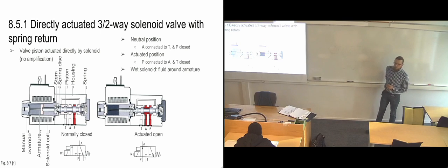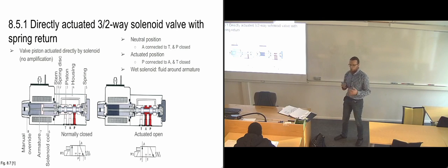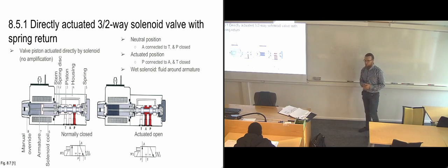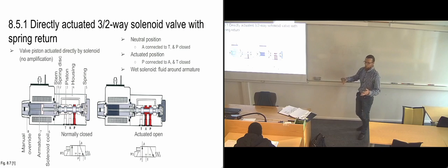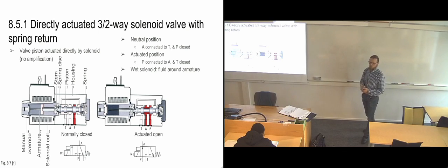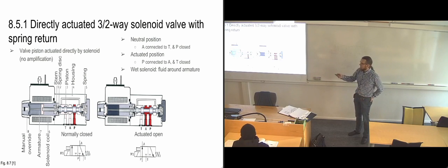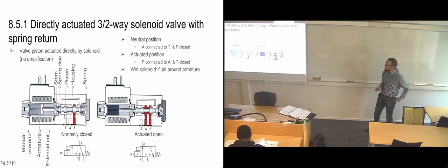So long as your hydraulic fluid is oil, unless it's one of those flame retardant ones with a lot of water in it, that's going to be very good, because then you've got metal parts that are covered in oil so that they won't corrode much. Usually the hydraulic oil has good corrosion resistance properties. So it's basically just protecting the internal parts of the solenoid from corrosion.